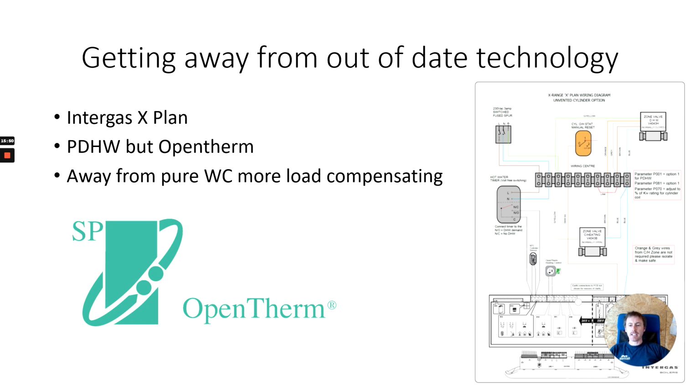Like say you're out most of the day and you get home, you might say, well, we'll go for OpenTherm because you'll have a quicker heat up time of the property. You don't just need to maintain the property. Thermostats that do this are things like Nests, not Hive, Nest I'd say, and other Honeywell products. Just because you've got a Nest doesn't mean you're operating on OpenTherm.